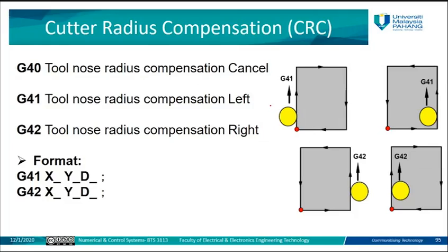For example, for drilling, we have drilling with a small diameter, drilling with a bigger diameter, drilling with a much bigger diameter, and so on. So each tool has its own diameter. Sometimes this diameter will affect our measurement, because when I place the tool on the surface, it's not like I place it in the middle of the surface. So there will be some difference in the measurement on the place.